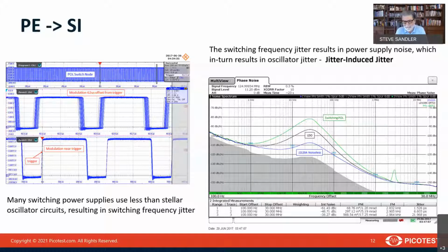And actually at about 2.8 megahertz, you can see that peak, and that peak is the switching frequency. So you might have expected that the switching regulator would have the most jitter, but the interesting question is, the jitter is about 25 kilohertz. Why would it be at 25 kilohertz when the switching frequency is 2.8 megahertz? The answer is because of that modulation. That modulation creates almost a millivolt of noise, and that millivolt of power supply noise causes that green trace.